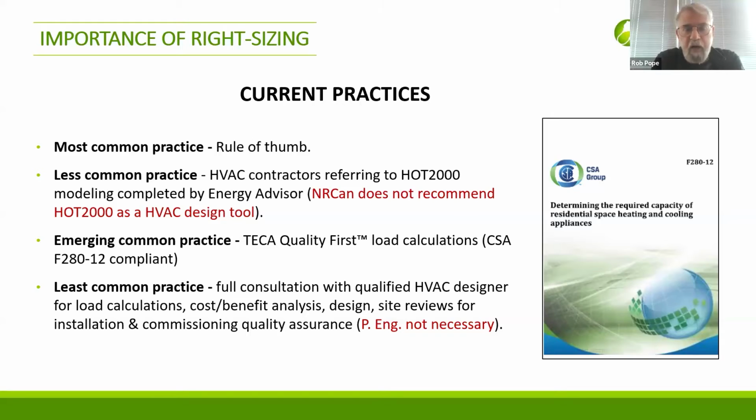The block load that HOT2000 does, although it's not verified F280 compliant software, will be close. If you do an independent load calculation with compliant software and measure it against a HOT2000 output, it shouldn't differ by more than 10%. If it's under 10%, it's probably good. If it's over 10%, then you have to check it. Something's not right.